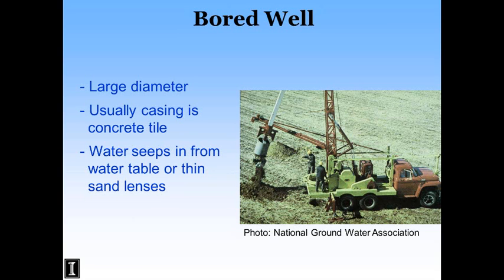A lot of times those units in glacial areas have very thin sand stringers, maybe 6 inches of sand separated with 30 feet of clay on each side. And those small sand units will hold water and allow water to move to the well. So you put in a bored well, which is large diameter and maybe up to 60 or 80 feet deep, and that acts as a storage basin. Those little seeps can continually resupply your well and keep enough volume there to supply you for the day.